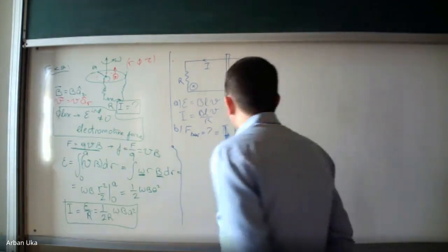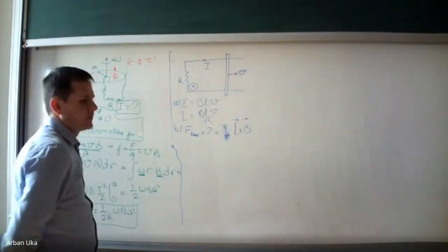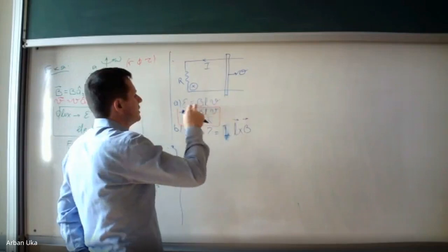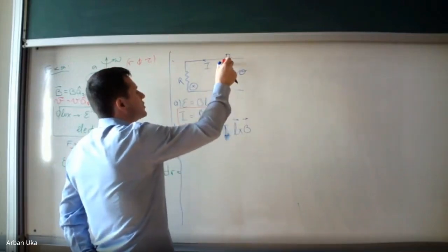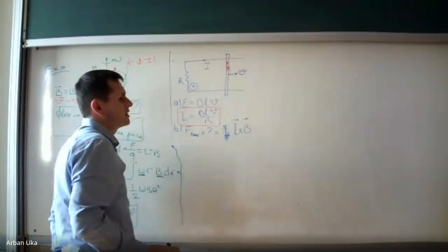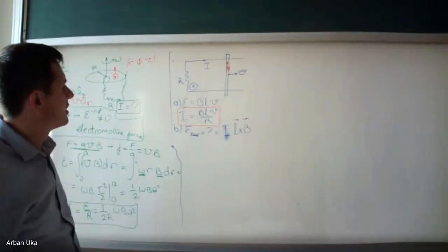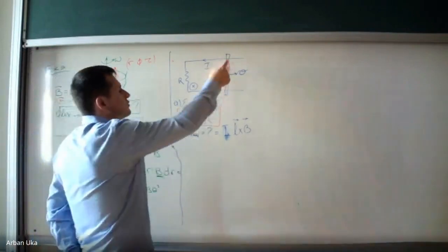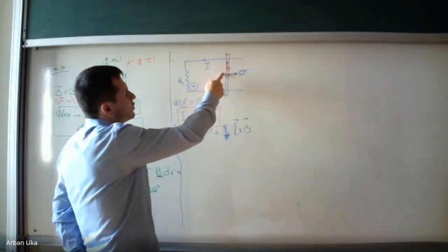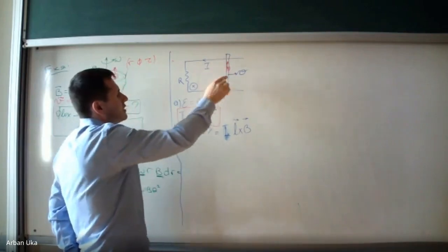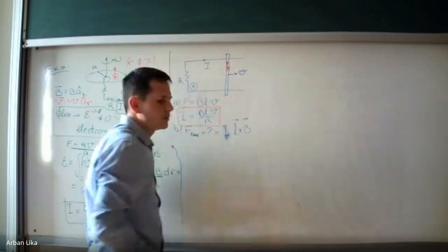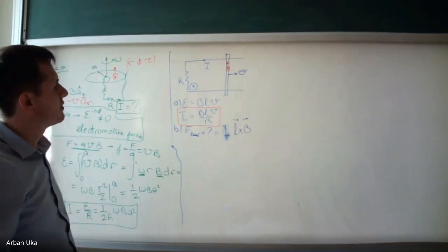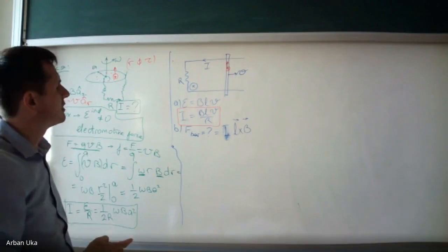In fact, this force is generated because once the current starts flowing, once this current is different from zero, we have positive charges which are moving upwards. These charges move upward because the EMF is created, and the EMF has to happen along this wire. There is no other way these charges are going to move. We cannot expect the charges to move out of the conductor to the left or to the right. So the EMF sets positive charges into motion in the single possible direction.